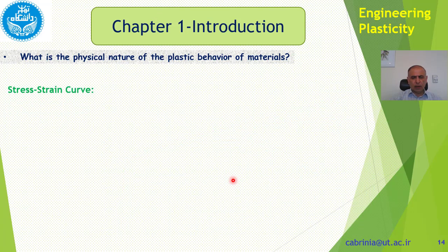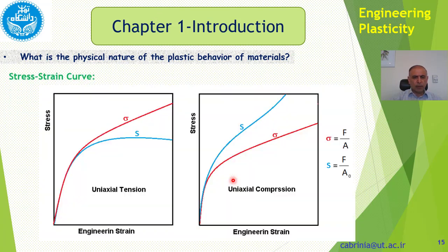I think that's maybe enough, but I'll show you another slide just to compare the compression and tension, because so far we have talked about the tensile test. So what happens if we use a compression test? Compression test is very similar to tensile test, except the direction of the loading is reversed. In tensile test we stretch the specimen. In compression test we compress the specimen.